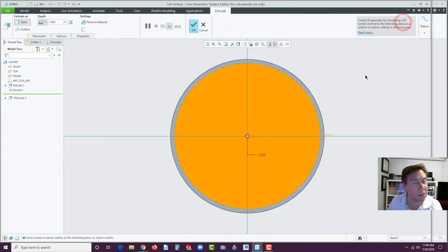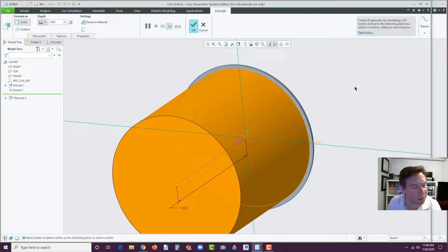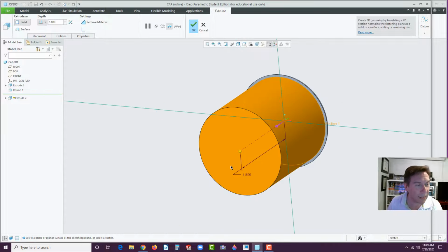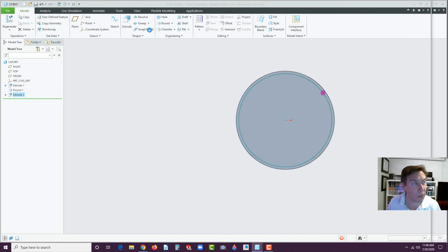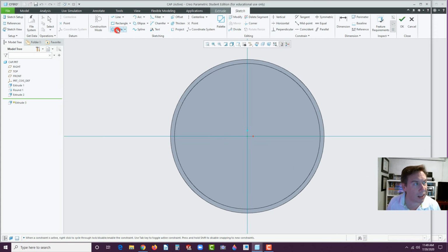Okay, but my best and brightest students do that because they're always looking for ways to integrate features, which is actually smart, but it's not smart that they're not looking at the dimensions. So that could be bad. All right, so I'm going to go ahead and change this to a 1/2 inch, hit enter. Select this face now, go to extrude, and now we could put the hole in. Also, don't try and shell it because the wall thicknesses aren't the same. So shell is only really good if you have a constant wall thickness. There is variable wall thickness capabilities inside the software. We're not going to get into that until the advanced class, so just be aware of that.